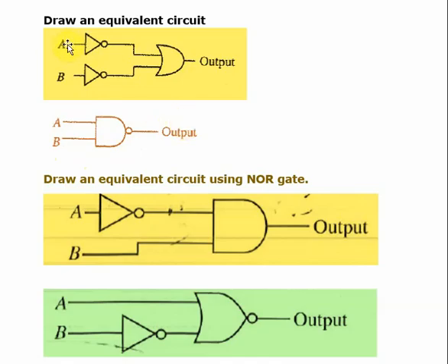Similarly if you provide 0 0 here, here 1, here 1, here 1, so same here you are providing 0 0, sorry, 0 0, the AND gate will give 0. So the NOT gate is connected. Then what will happen? Opposite to that, the output is 1.